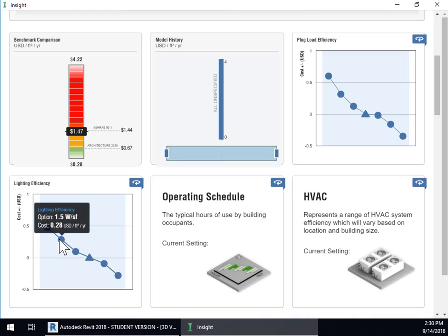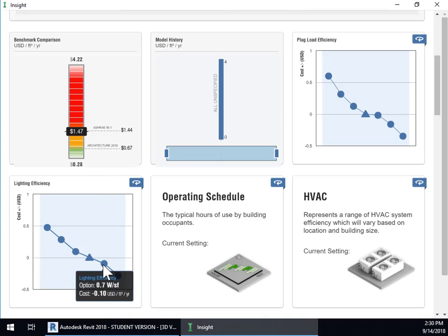So you can see very little increase here makes a tremendous impact on the amount we would pay. And it would actually put us above the ASHRAE 90.1 if we did that. If we got the lighting down to 0.7, which would be easy to do by adding daylighting. Now remember, we didn't run any daylighting, so we could probably get this down just by having daylighting and